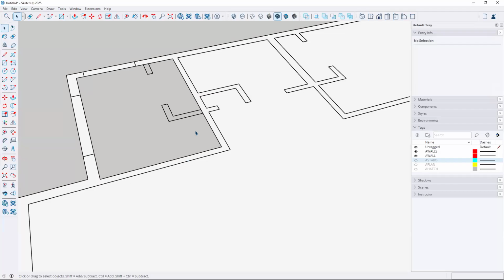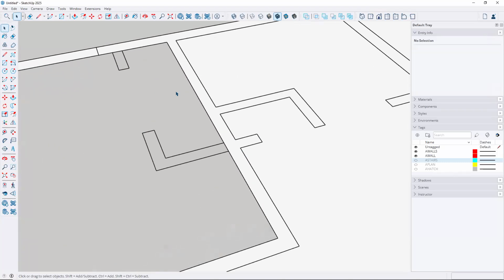So it's just leaving the outside walls and the inside walls, but now I have to come back and put in the walls here. So what I'm going to do now is draw a rectangle from here to there. Notice how it fills everything up. That's fine. Tap the space bar, select that surface again, and delete it. So this is maybe a little time consuming, so I'll try a different way. I'm going to type L for line. I'm just going to draw a line from here over there, and I'm just going to trace this.